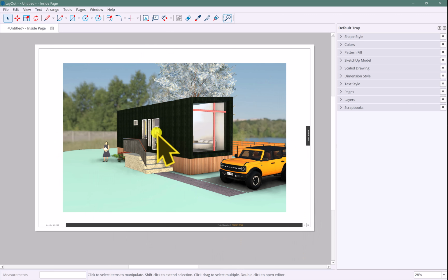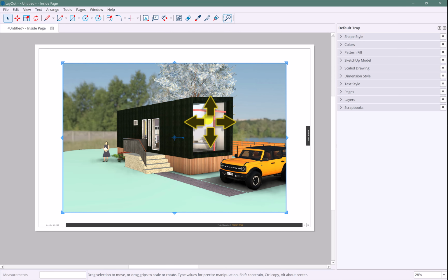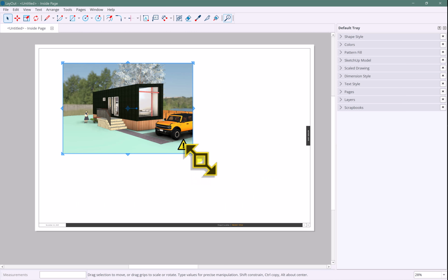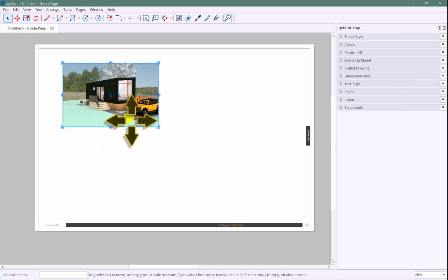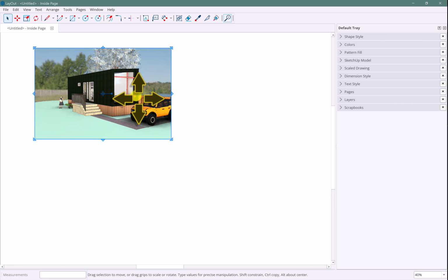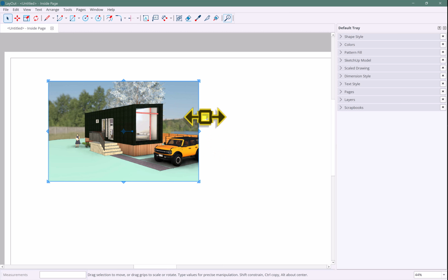And if you're familiar with AutoCAD or Revit, the sheet interface is pretty similar. There's kind of a viewport. And this viewport, if you click on it, it's your last view in SketchUp before you sent it over to Layout. These can be resized using what are called grips. And sometimes you'll get that little yellow icon saying, oh, I'm updating.